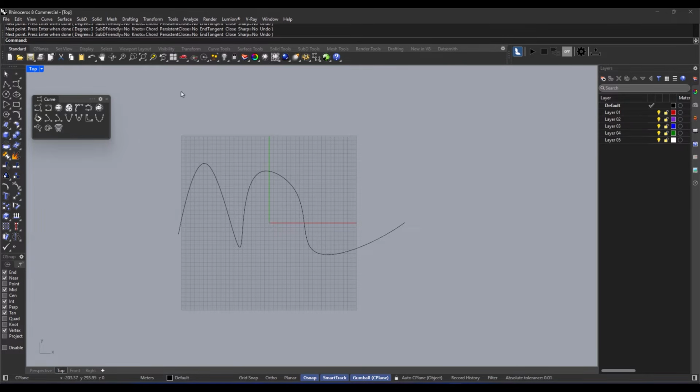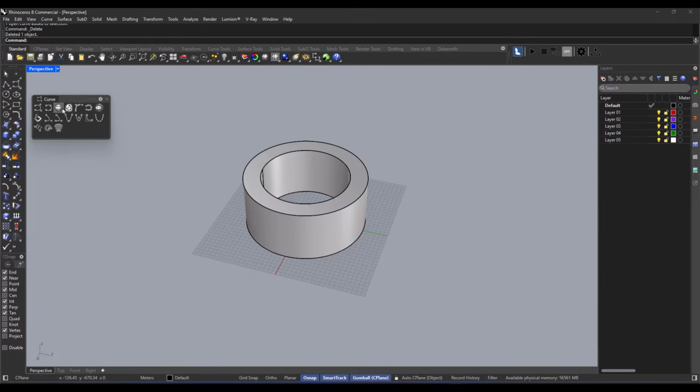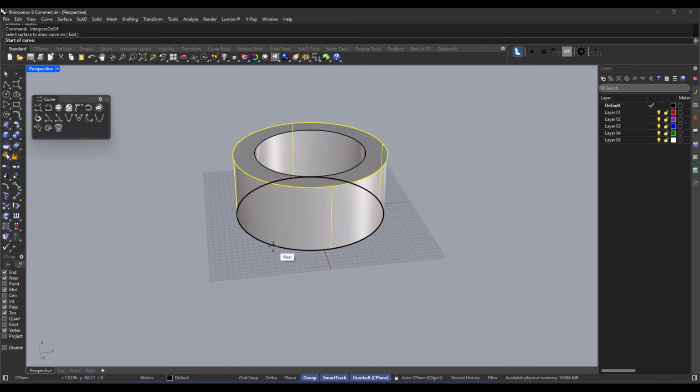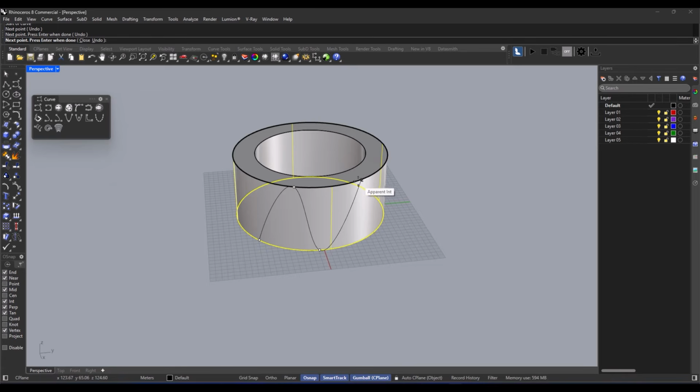Pretty straightforward, huh? Now, if we're talking about interpolating points on a surface, it's kind of similar. This command draws a curve through selected locations on a surface. So first you select a surface. And if you want the infinite plane, just type IP for those options. Then you pick the start of the curve again, and you keep picking those next points. And don't forget to press enter.